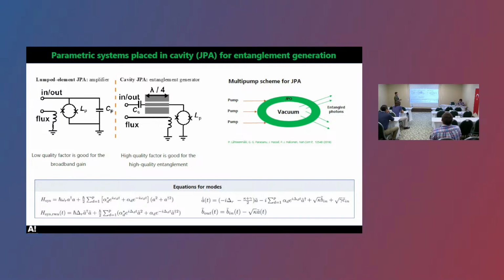If we want to utilize this device as an amplifier, we have an additional line that we use as a pump for our signal. The idea here is to transfer energy from the pump, which we guide through, let's say, flux to the SQUID. That is one example of how energy can be transferred via a flux parametric signal to the SQUID loop. Then we transfer the energy to the signal that reflects back, and that's amplified. If we tune the frequency, we can get parametric amplification just like a regular mechanical parametric amplifier.